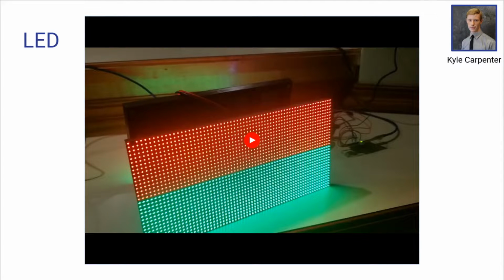However, there have been some difficulties with the display, as there's not very much documentation available on the internet at the moment. The display has its own documentation, about 2 pages long, with just technical specs about electrical characteristics. However, what we do know about the display is there's 384 bits that can be shifted into its 24 LED controllers every time. And those 384 bits are then latched.